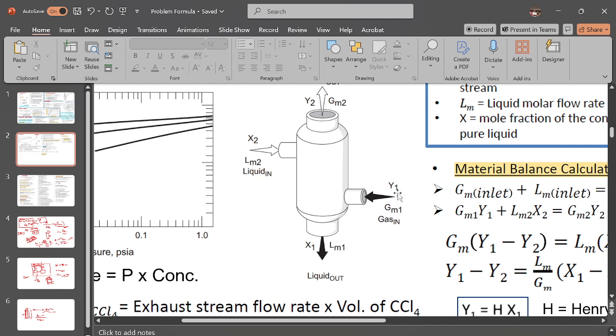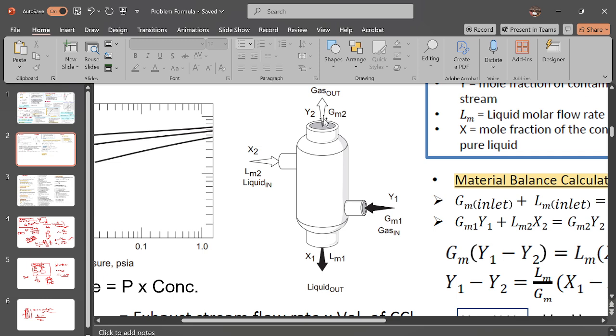So what's the concentration? 3%. What is the concentration out? 0.03%. Same, I know the concentration of water coming in and going out. It's pure water, so there is zero sulfate concentration there. And going out, what will be the concentration? I know. And what will be the flow of water? That we don't know, right?